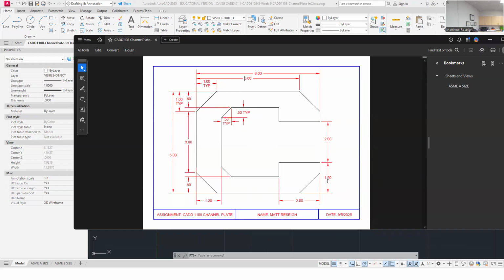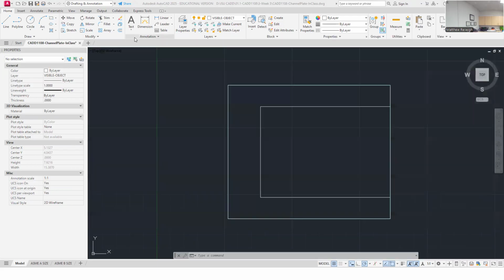But essentially, I've got to offset maybe 2 inches to get these little line segments here. And then I need to offset 1.5 inches to get this one across. So let's do that. And then I'll trim them to look like this and how they fit against that line that I just did. I'm going to keep doing the offset command, and I'm going to offset not 1.2, that's the last data I input.